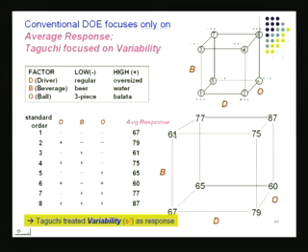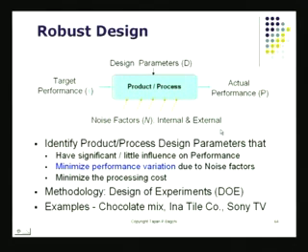So when I've got this experiment running there, take a look at what is the impact of the different factor settings on S square there. So I measured S square all around. So I'm trying to look not only at the effect of the different factors on average response, but also I'll be looking at the variance of that response. This is the idea that was exploited when Taguchi came up with a scheme to develop robust design.